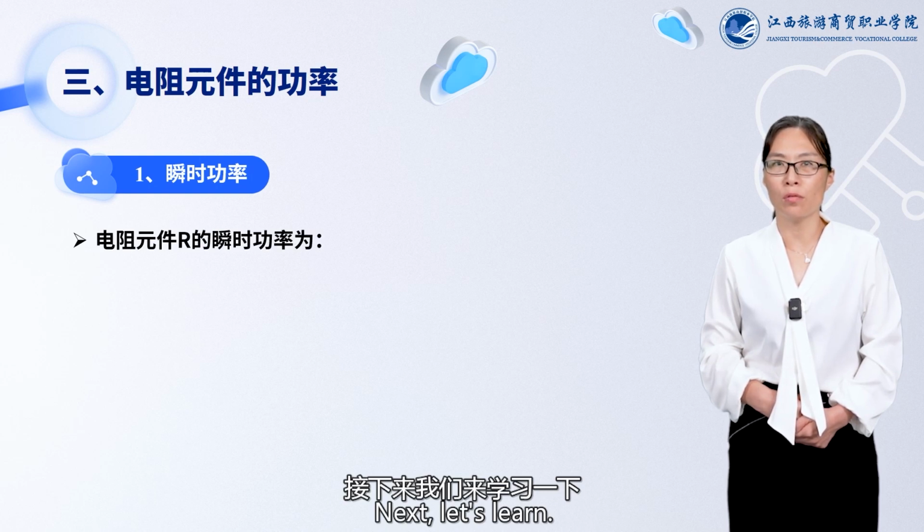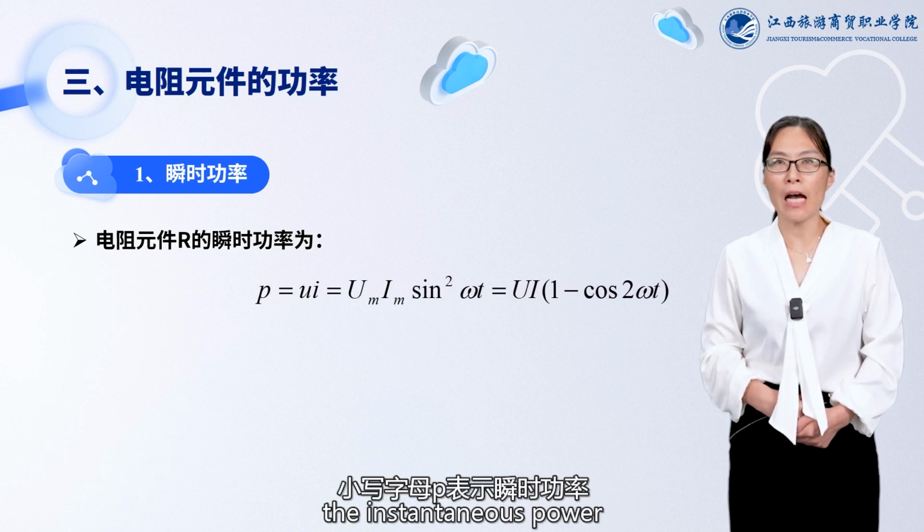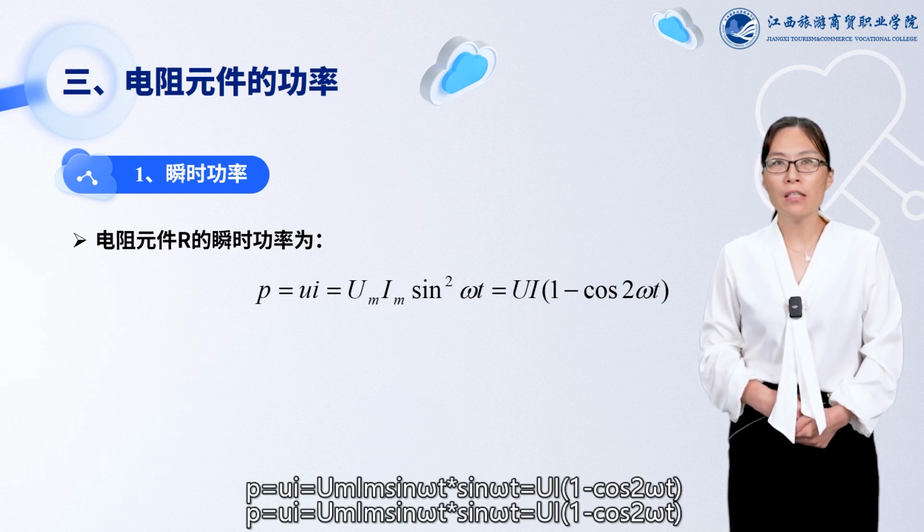Next, let's learn the instantaneous power of the resistance element R, the instantaneous power being the lowercase letter p. p equals ui equals Im sine omega t times Um sine omega t equals UI times (1 minus cosine 2 omega t).